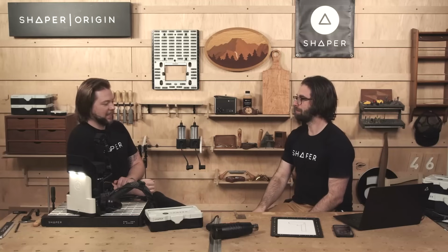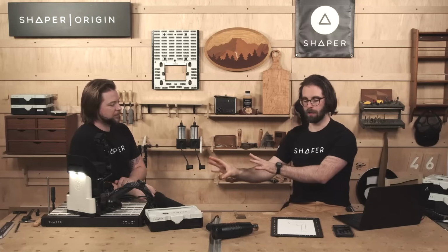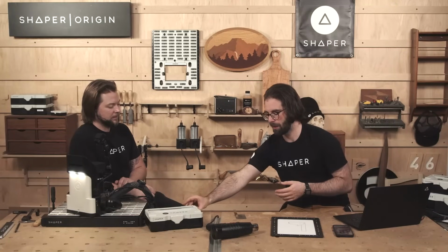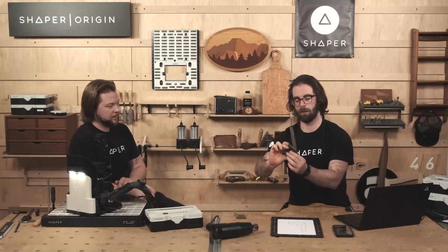Shall we get back to it? Let's do it. Okay, so the third way. We've designed with Origin. We sent that Origin design into Studio so that we could add more stuff. We designed some rectangles and shape-shifted them together in Studio. But we've got this really complex combo square that I want to get the actual profile of. And this is what Trace is really good for.